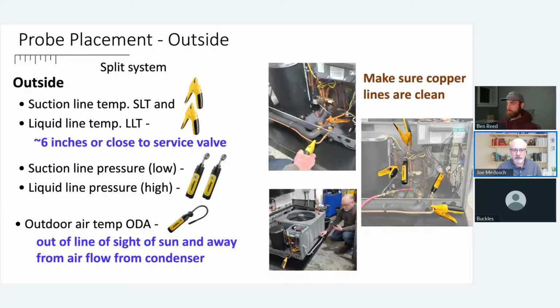So that's one of the probes that most people are missing, the outdoor air temperature. Clarifying, you cannot just enter the outdoor temperature and get the Vital Score, benchmarking, or anything else. You must have all 9 probes connected and reading in order to get all of the major benefits you're getting from measureQuick.